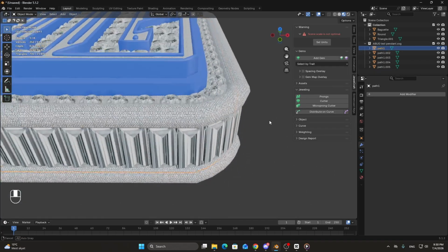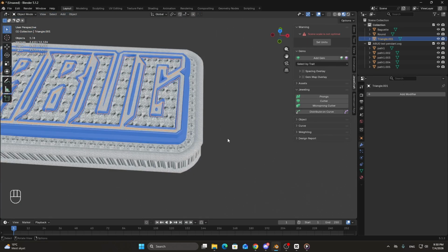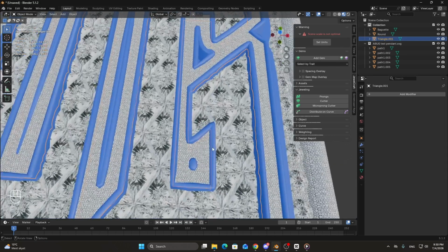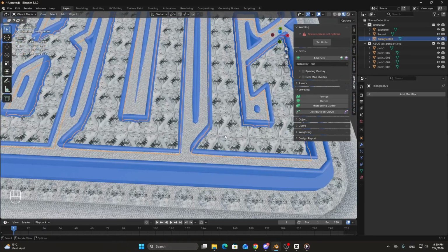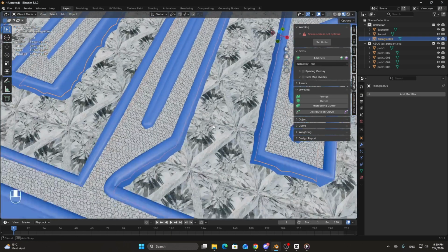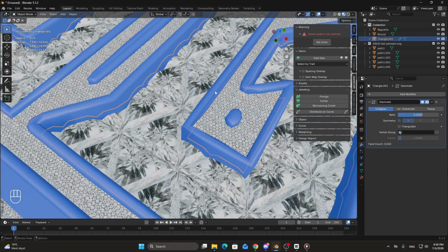So re-cube project this and scale it by 1.5. The next one is the inner layer. We can decimate this 0.2. The triangles: if you have very small ones, you can go ahead and decimate them, but honestly 7k vertices for this is not bad. But if you have to, as long as they are merged by distance, like I mentioned earlier, they can be decimated by like 0.6 and still look fine.